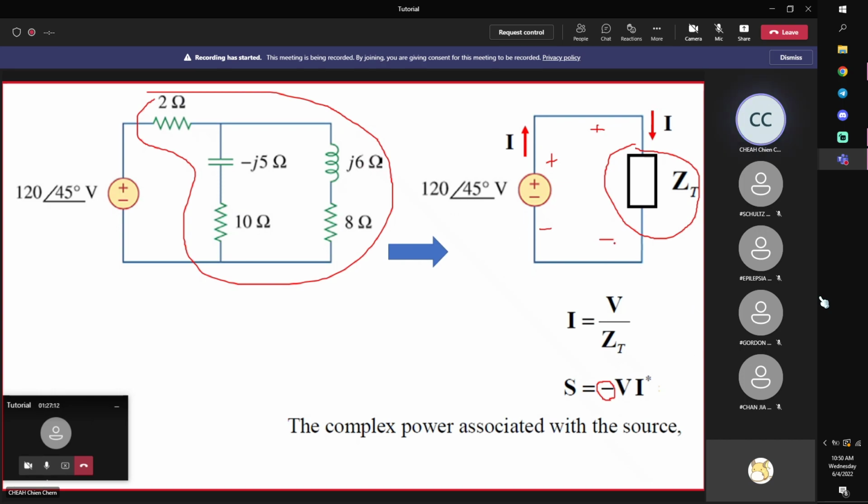Passive sign convention is very easy to remember. Water flows from a higher level to a lower level. For active elements, if you want to pump water from a lower floor to a higher floor, you need an active source, which supplies energy. So for power engineering, the convention is that consuming energy is positive, supplying energy is negative. That means by convention, by nature, current flows from high to low. If it is the other way around, you put a negative sign.